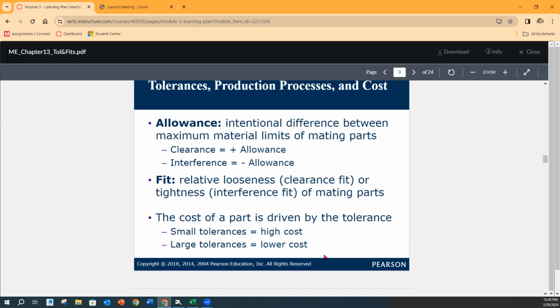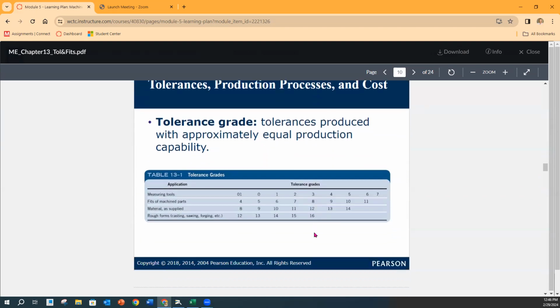So each and every one of those dimensions corresponds to not only whether it can be made, but what it is going to cost. A good designer will literally think about each and every one of those dimensions. It's not a matter of SolidWorks or Creo putting all my dimensions on and now it's done for me. No. You are the human. You have the brain. You have the know-how and the knowledge to make this decision. This is directly related to what you do, and that's a really, really important part of the design process.